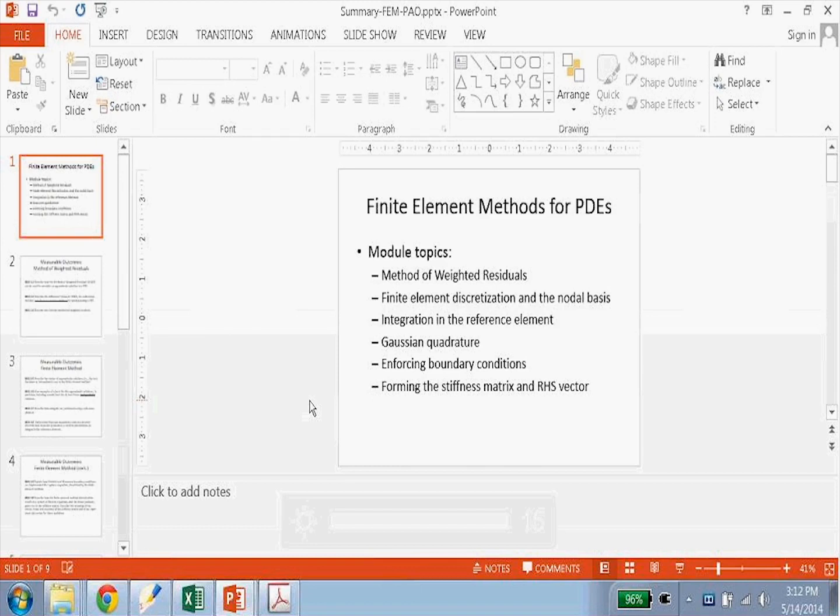So where do all the bits go? Here, if we had a Neumann condition, this is where this contribution would go. This term here is going to give us the stiffness matrix, and this term here is going to give us the right-hand side. Let's just remember how all that goes together conceptually. So this one here is going to go to our stiffness matrix. This one here is going to go to the right-hand side.